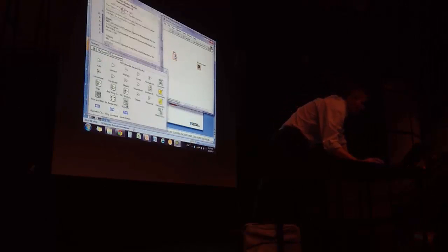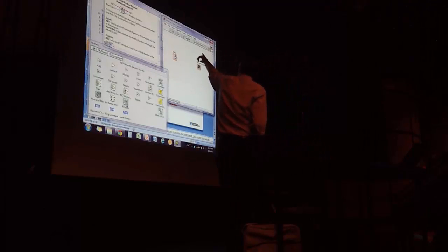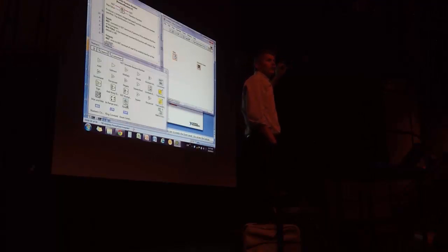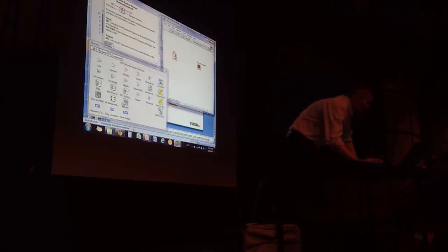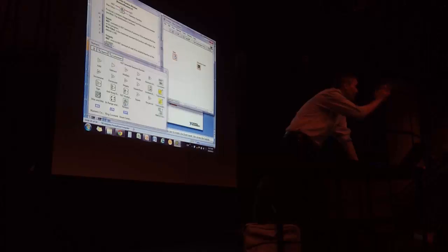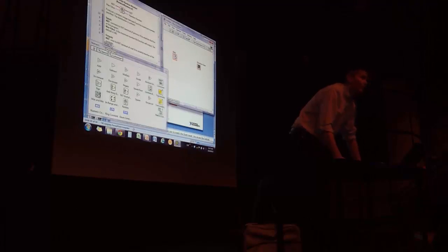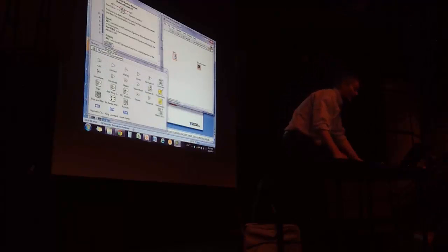If I go over the random number generator, it produces a random number between 0 and the maximum number specified. And the max value, if I don't specify that, the default is 100. So it will generate for me a value between 0 and 100. If I would like to have a value generated between 0 and 1, I would have to wire just a 1 to this input. So Ctrl-H, very important and will help you out. You can get much more detailed help. You see this question mark, I won't press it. But then you get detailed help on this function, or any function that you have.